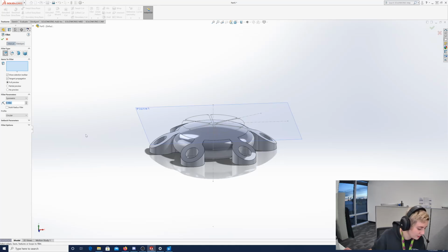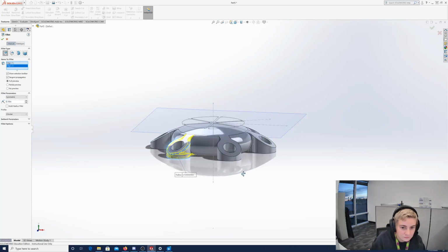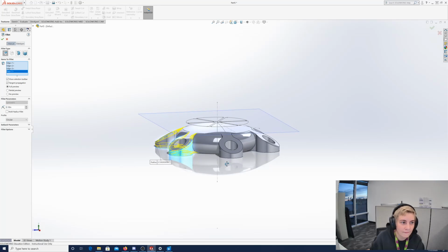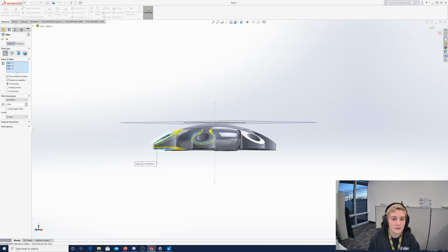So that's on page 7-30. And it looks like there's several different fillets they want us to add. So the 0.0625 inch ones, we want to select these top and bottom edges here on all 6 little tabs. It's going to be 12 edges total. We don't want a face. So when you do this, make sure you're watching what shows up in this box over here on the left.